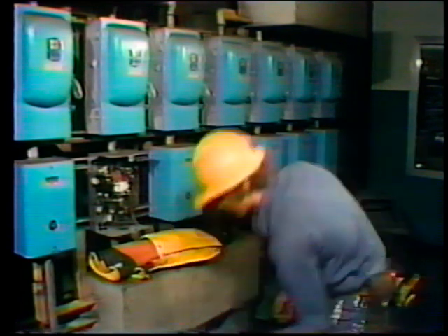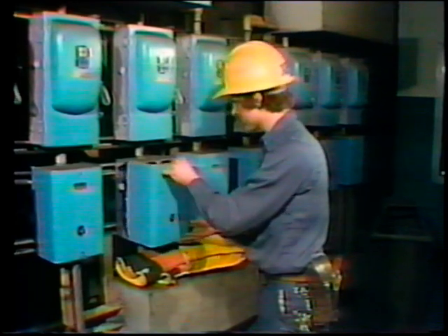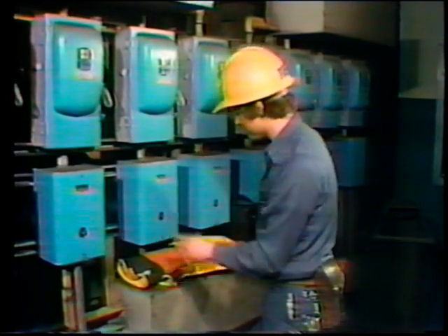The electrician must now repair the broken wire. Repair is the fifth step in troubleshooting a controller. He replaces the cover before leaving the area. The power supply breaker must be tagged in the off position. The power supply breaker is tagged in the off position according to plant procedures. Always follow your plant's procedures when working on electrical equipment.